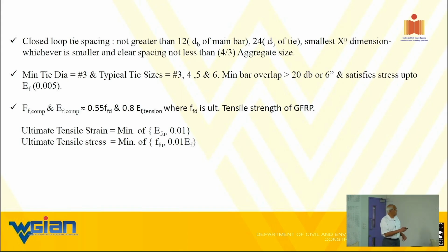What they did not observe here is that this is true for an individual bar, but not a bar confined in concrete. See, we are talking about a realistic scenario. So that's why I keep encouraging you to put a strain gauge on the bar while you're testing a column.